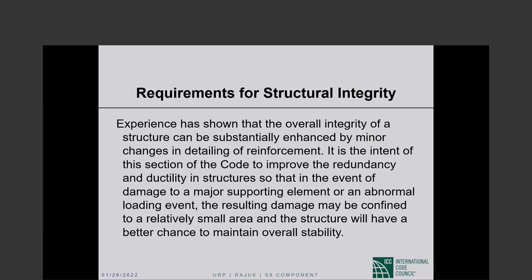The maximum limit of gap between two layers of reinforcement in a beam, top or bottom. The questions are framed in a very strange way. So the minimum gap between the upper layer and the lower layer of reinforcement is 1 inch. So the question, if I understand this, is: is there an upper limit on that gap? The answer is there is no upper limit.